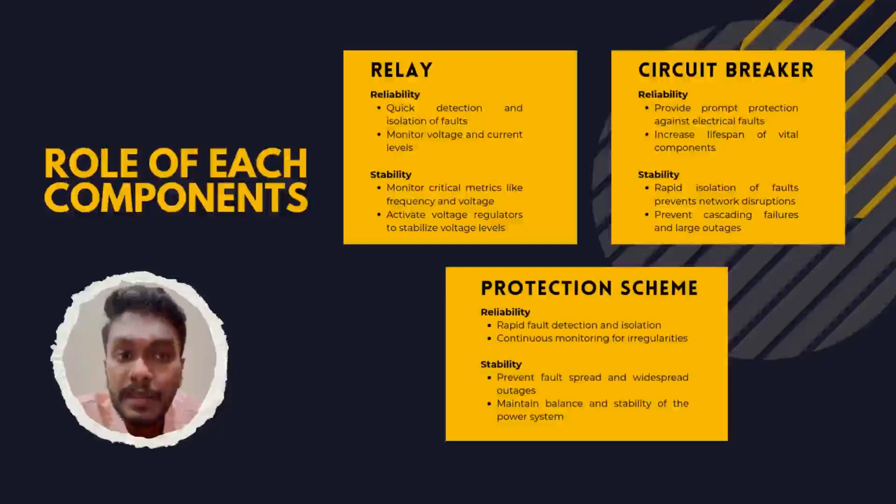operational. Circuit breakers enhance power system stability by swiftly isolating the fault, preventing it from causing broader network disruption. This rapid fault containment helps avoid large-scale outages and potential cascading failures. Modern circuit breakers with features like remote control and monitoring allow for efficient administration and quick restoration of the services.